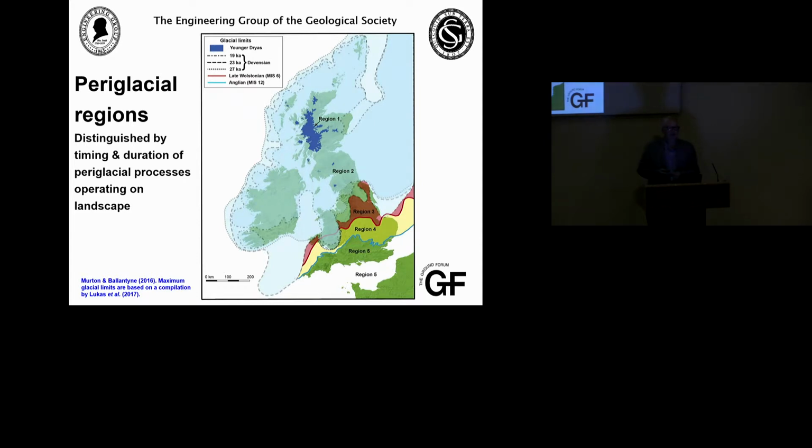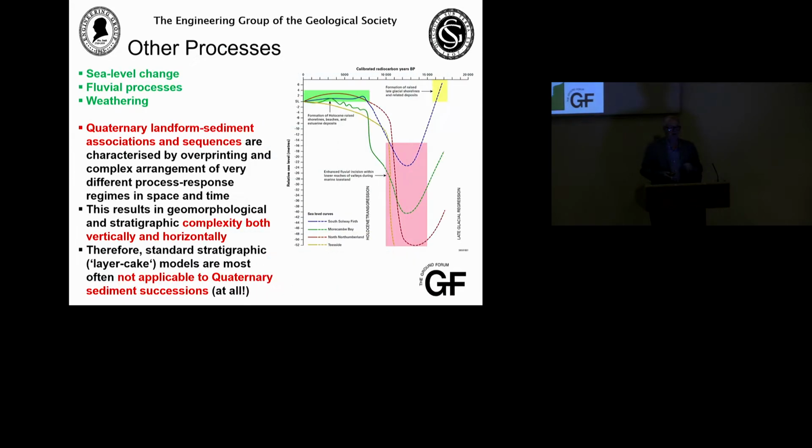And you can start to see from the maps that are appearing, we're starting to break it down into regions. If we've understood that climatic history during the past 2.6, 2.7 million years, we can start to predict the ground conditions. We can start to predict the variability. We can start to reduce the uncertainty in terms of what we might expect in those particular areas. So these paleogeographies, although physical lines are perhaps over-egging where the ice actually went, understanding the broad regions where they've experienced those different climatic conditions becomes extremely important in the development of these ground models in terms of potential prediction.